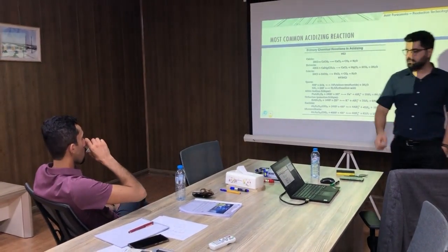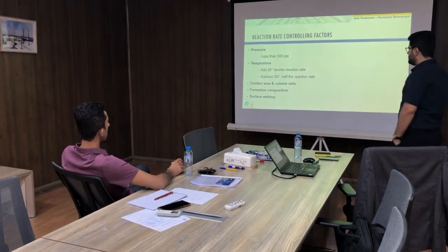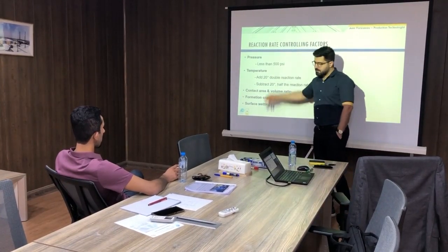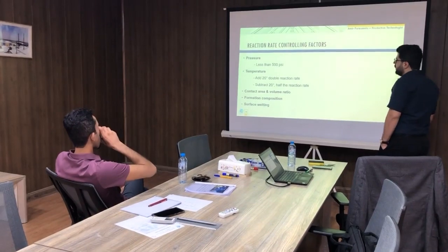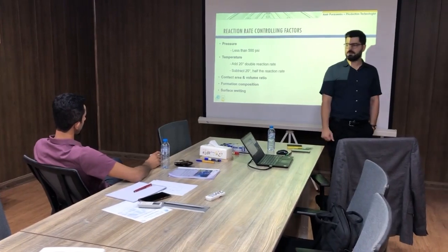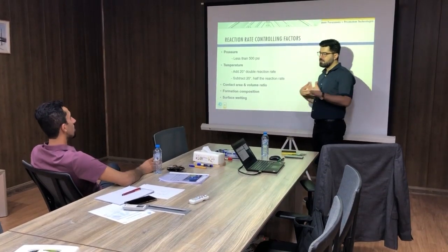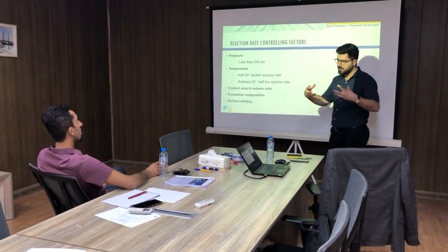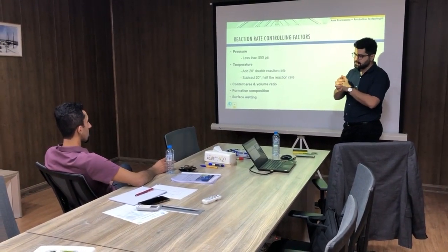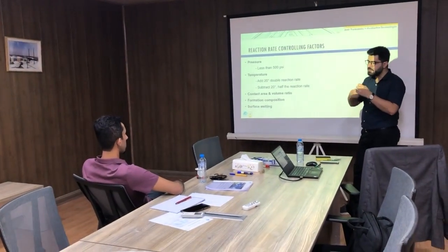These are different mineralogies' reactions based on different acidizing. Consider reaction rate limitation. If you have a pressure less than 500 psi, this low pressure limits your reaction. Your reaction is decreased by this reduction of pressure. If you have a high pressure, this high pressure gives you an opportunity to have a better reaction between these molecules. Decreasing your reservoir pressure leads to reducing these reaction rates.